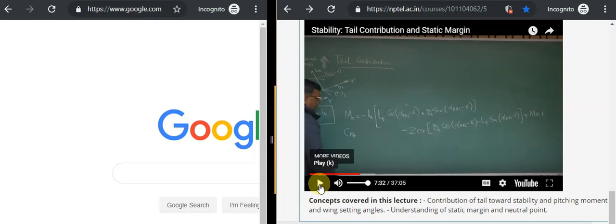Okay. The only difference is that, minus Z of CG, you have the same expression but with dt cos of alpha FRL minus epsilon minus LT, which is then again with the sign, and it is actually downward because of the downwash epsilon. It's obviously there in each of the expressions, and it is LT because of the tail. You had it negative and downward, and you're just going to add to this expression, and after it is plus MAC at epsilon.